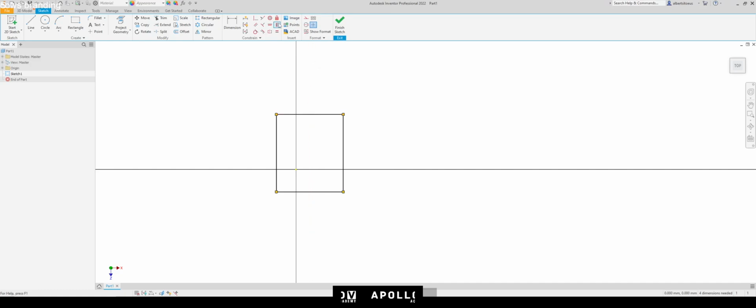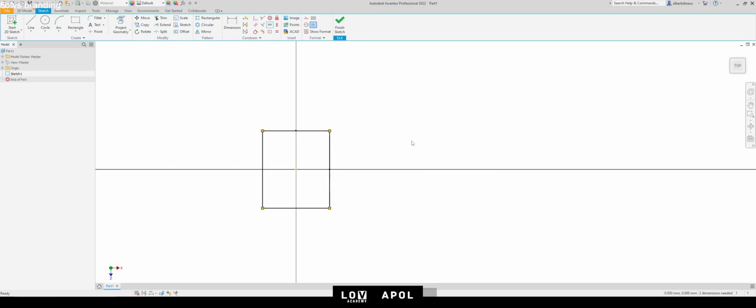So here we'll just use the vertical constraint on the middle point over here to the middle point over here. That yellow dot is the origin, which is the origin of the entire file. And you have to ground everything to a single origin point because that is where everything started. Think of it like the Big Bang. But in this case over here, we'll click there.